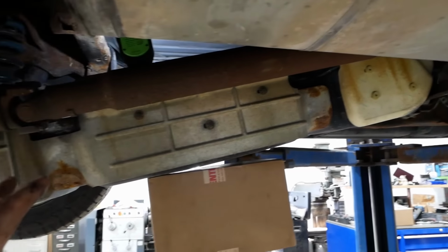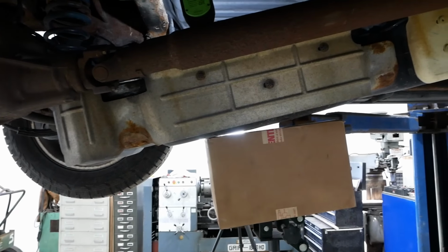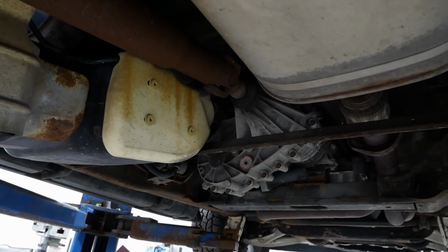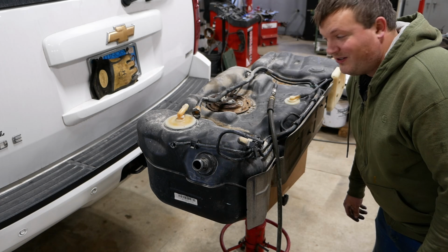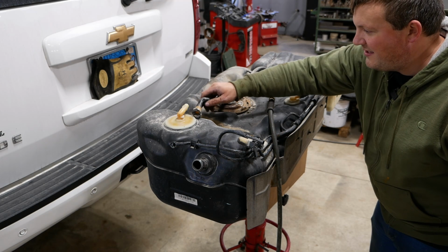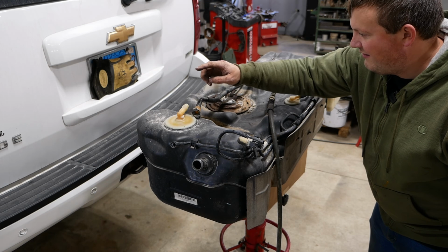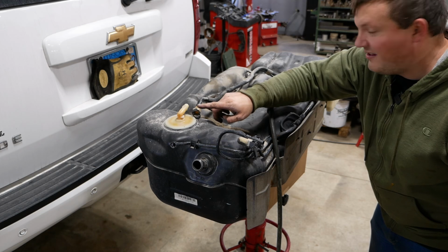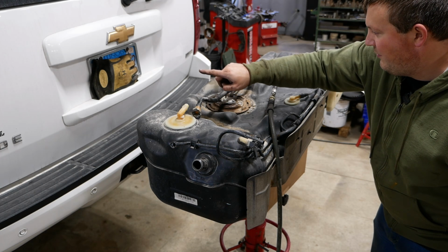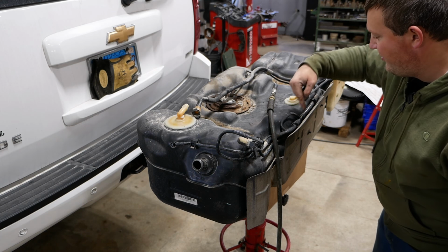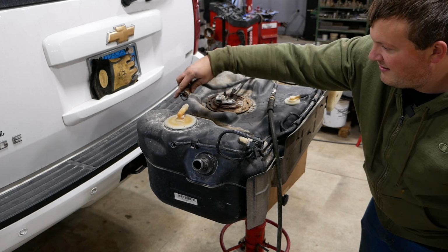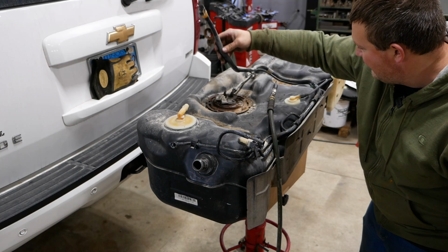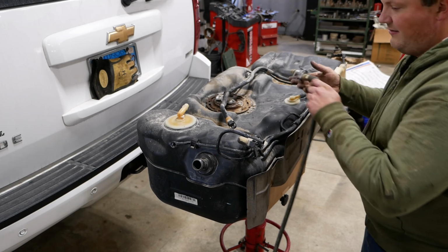It's kind of weird. You got to go down in the back and then slide it to the rear, because that cross member up there, the tank fits above the cross member and the cross member cannot be removed. That was a struggle. The biggest problem is this vent line. It literally runs from here to here. But GM decided in their infinite wisdom to run up over a cross member and then make a giant horseshoe shape. So you got to reach up underneath the thing and disconnect this giant, whatever it is, 3/4 inch disconnect. Anyway, we got her out.